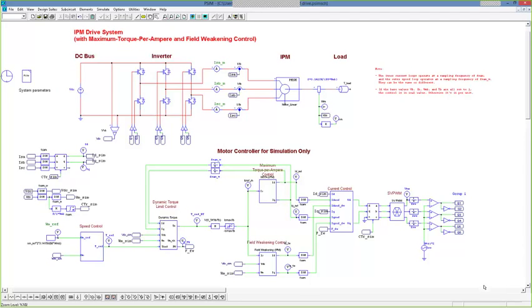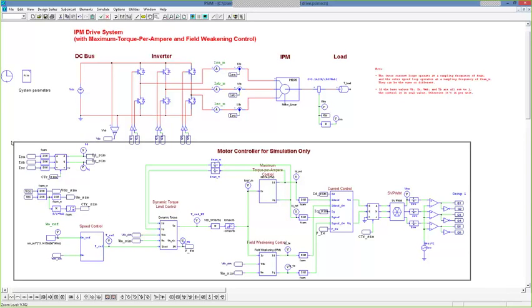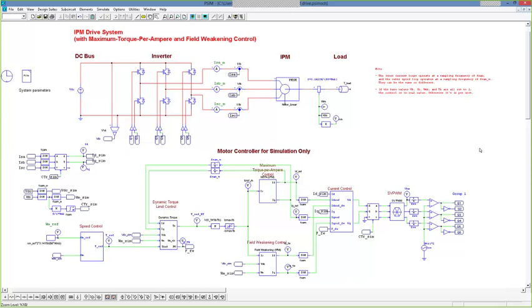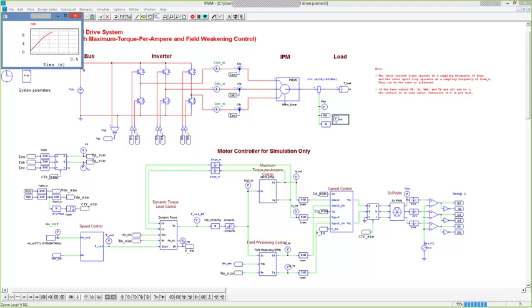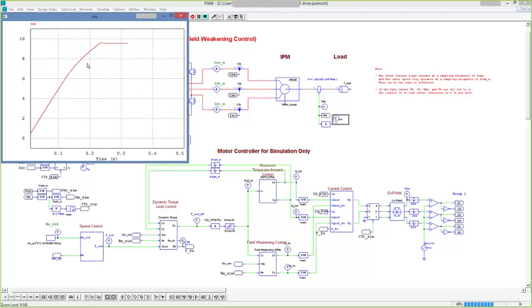So this will get turned into just general C code. If you want to put this on a DSP, you'd have to then define what the PWM timing frequencies and the interrupt routines and all those sorts of things would be. This would just handle the basic translation. We can run this and look at things in real time, like a runtime graph as it plots, and we can see here's the response as it hits steady state speed.